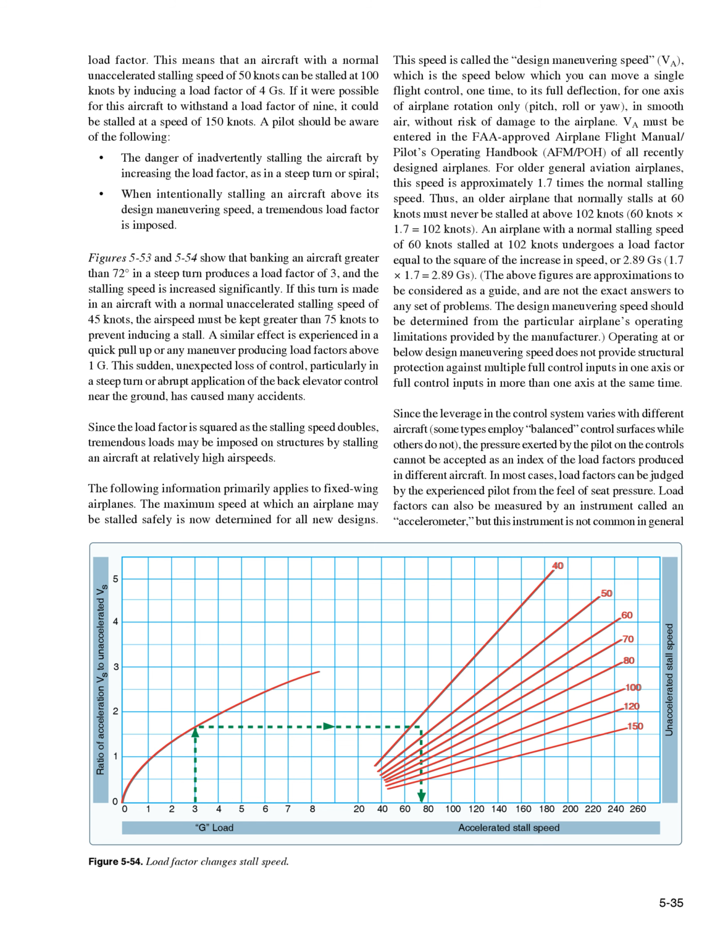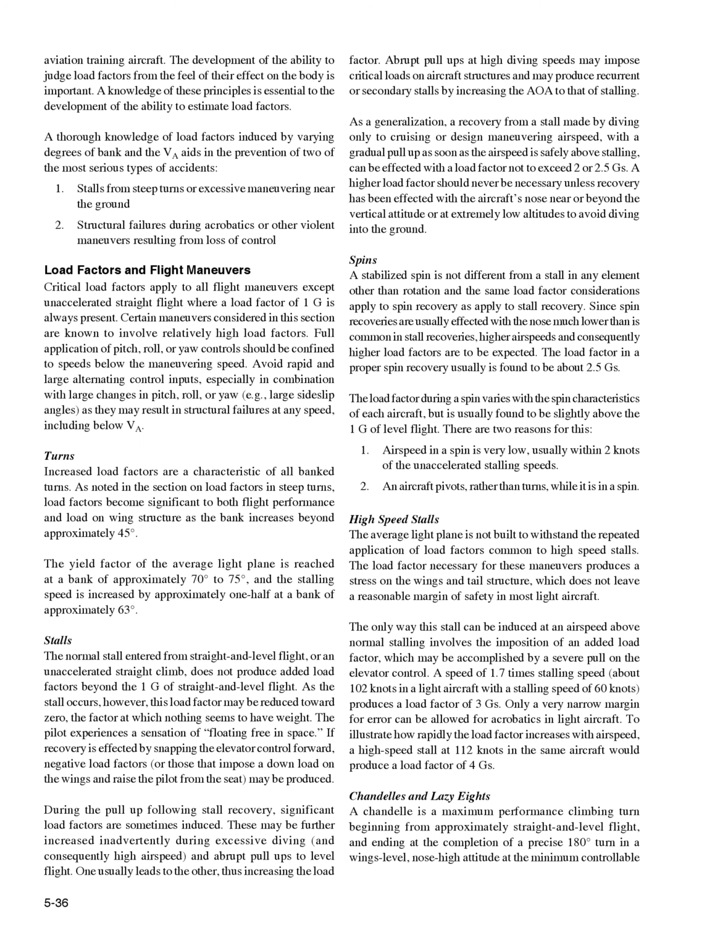Since the leverage in the control system varies with different aircraft, some types employ balanced control surfaces while others do not, the pressure exerted by the pilot on the controls cannot be accepted as an index of the load factors produced in different aircraft. In most cases, load factors can be judged by the experienced pilot from the feel of seat pressure. Load factors can also be measured by an instrument called an accelerometer, but this instrument is not common in general aviation training aircraft. The development of the ability to judge load factors from the feel of their effect on the body is important. A knowledge of these principles is essential to the development of the ability to estimate load factors.